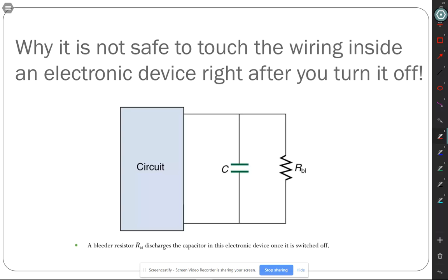We agree? Now, what if that 10 milliamps or more is going across your chest? That brings up a real safety issue. Because I like to breathe. I do it all the time. And the way we breathe is first, we relax. And when we relax, we expand a little here. And atmospheric pressure forces air into our lungs. Right? You cannot breathe without atmospheric pressure or some external pressure pushing air in. And then we tighten up these intercostal muscles, pull our ribs together, push the air out of our lungs.